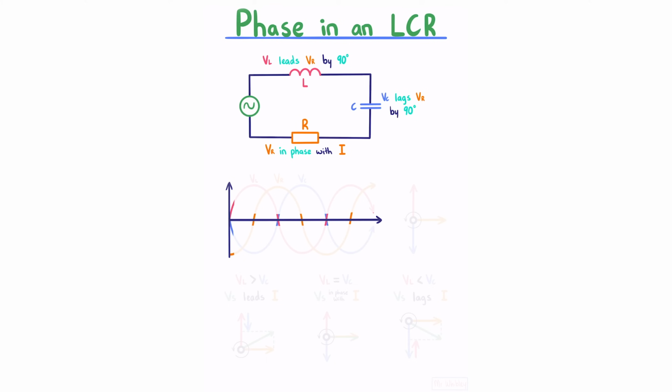We start with our voltage of our resistor at a negative maximum, which means so too is our current. Because our current is at a maximum, it isn't changing, meaning that we have no voltage produced by our inductor, or in other words, a back EMF. And our capacitor is uncharged, analogous to a pendulum at its equilibrium position, right before it starts to charge again.